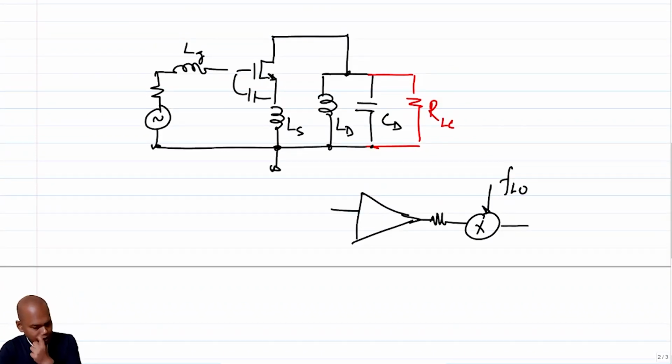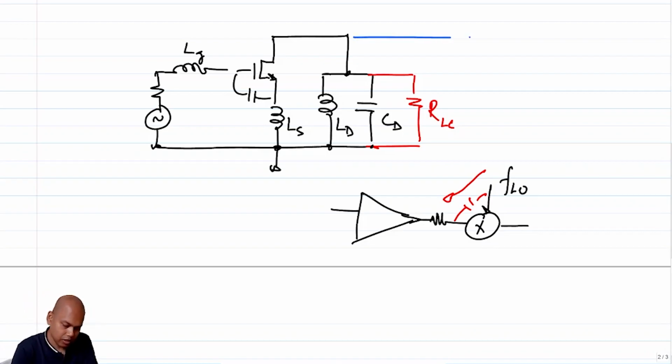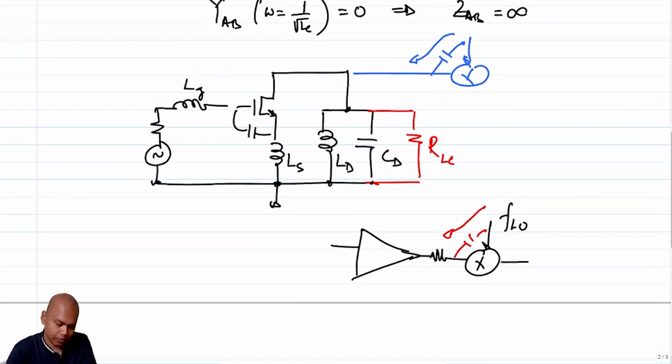So there are a couple of things that tend to happen. One is, if you recall our discussion on direct down conversion mixers, or even superheterodyne kind of mixers or receivers, then you probably will remember that normally there is a capacitance associated between the LO port and the RF port of the mixer, which causes some feed through from the LO to the RF port, which essentially means that there can be a feed through from this mixer to the output of your LNA, right? Let me call it an LO kickback.